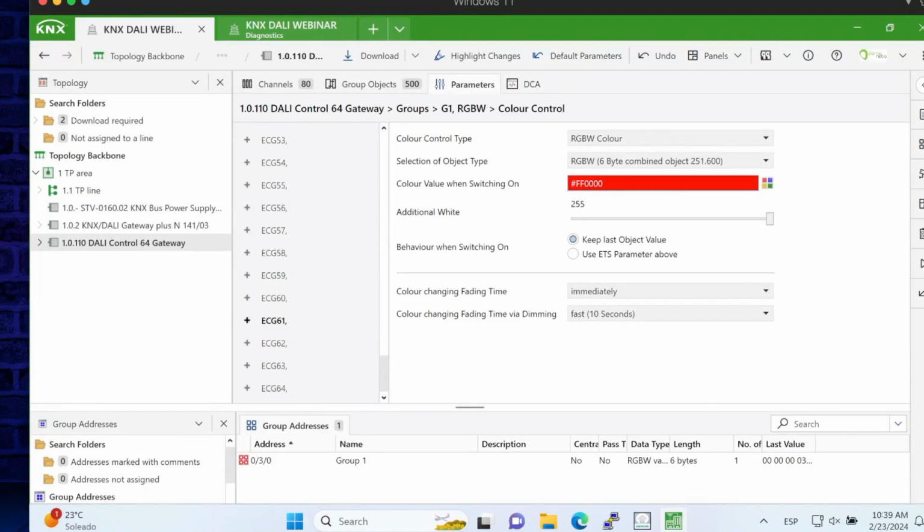That's very powerful. If I want to do exactly the same to control 64 loads, lights or whatever, in a dimming way, not on-off but dimming, with pure KNX, it's going to be very expensive. Why? Do you know how many 4-channel dimming modules I need to implement that? 16. It's crazy. In this situation, with only one gateway, I can control all of them.